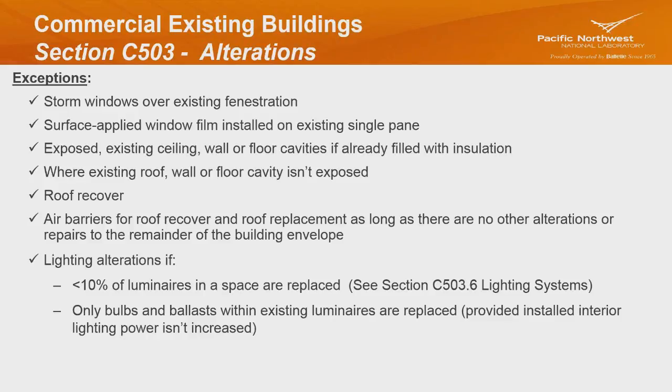In Chapter 5 of the 2015, you'll see two numbers for lighting. In the scope for the lighting, it shows 50%. And then the actual lighting section, which I've provided to you here, C503.6, says 10%. With that said, the intent when the 2015 IECC came out was basically that it should have been 10%. It's not. That 50% is in there as well.